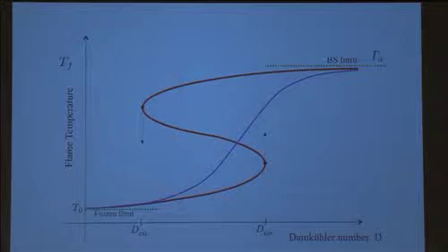The red one is the more typical and the more interesting, because what it identifies is ignition and extinction criteria. So, for example, if you start from the Burke-Schumann limit and you start decreasing the Damköhler number, then it's no longer a reaction sheet; there will be some leakage of fuel through the sheet on one side and some leakage of oxidizer on the other side, a small amount, but they will leak through, and the flame temperature will decrease slightly from the adiabatic temperature.